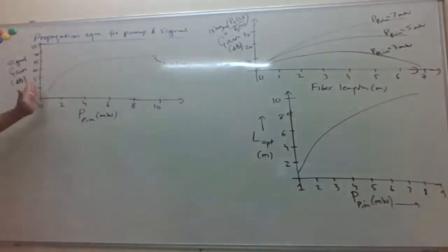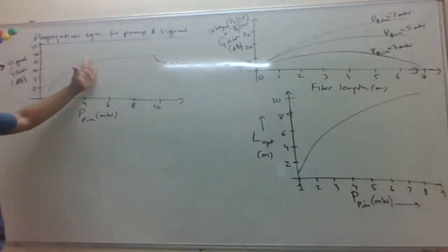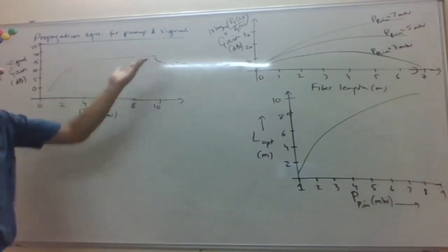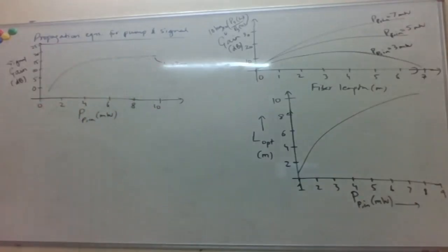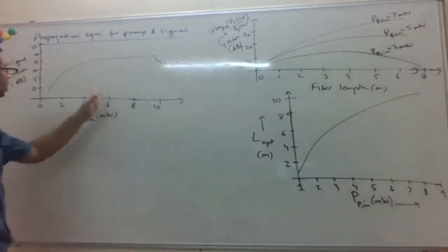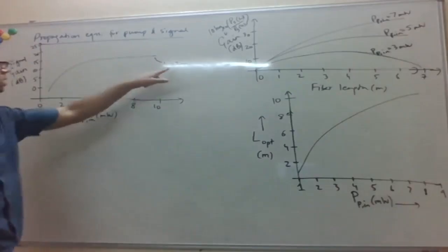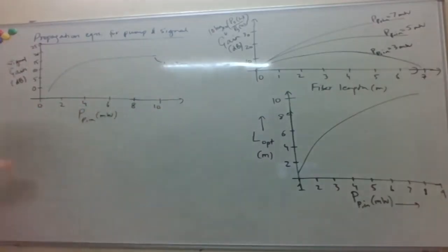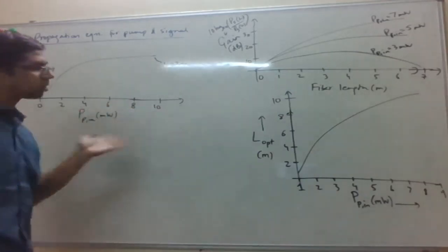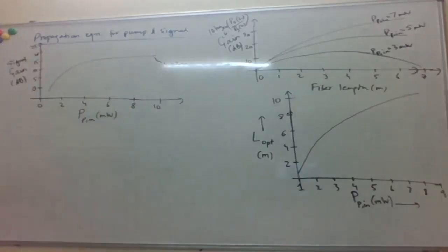So you can see that the gain increases up to some level of pump power. After that, it saturates. Increasing pump power doesn't give me anything. And that's because beyond a certain length, the pump power has already decayed. So increasing pump power doesn't give me much improvement.